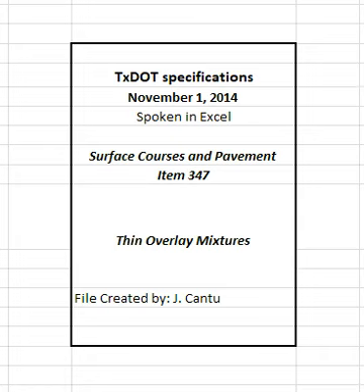5.1.2 Measured percentage. The average measured asphalt percentage from each sublot will be used for payment for that lot's production when the measured percentage for any sublot is more than 0.3 percentage points below the JMF target asphalt percentage or less than the minimum percentage specified in Table 6. 5.2 Aggregate. The aggregate weight in tons will be determined from the total weight of